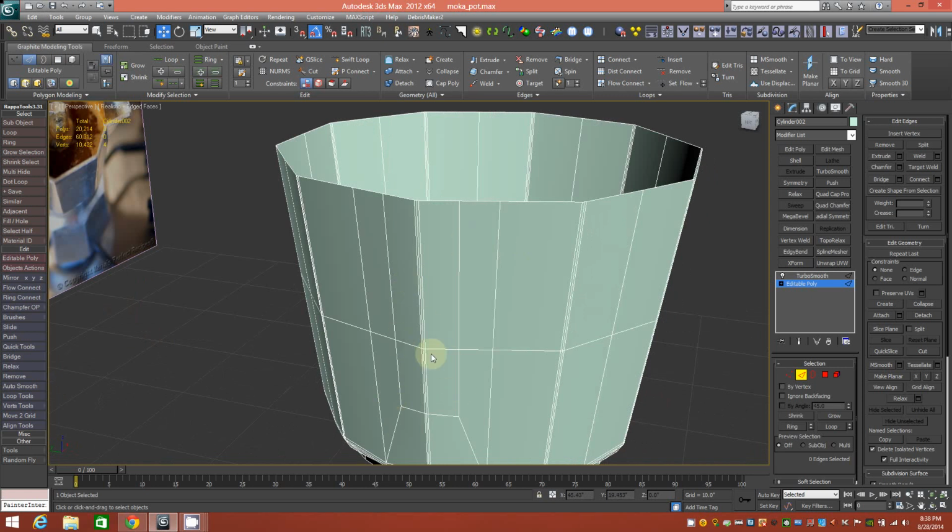And we could have actually used inset to achieve this same result, except that if we grabbed all of these faces and we did an inset, it would have created a new additional group of polygons right in the middle, and we would have had to remove these top faces and then straighten the border edge again and make it planar.